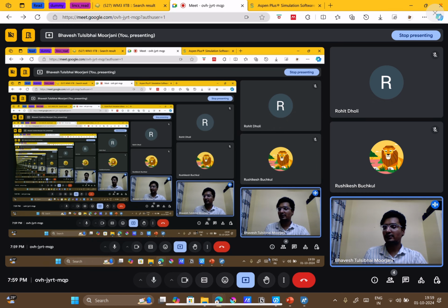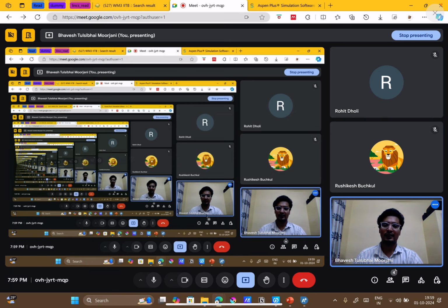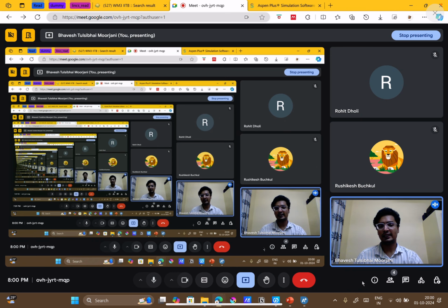So water is used to separate acetone from this mixture. So acetone has an affinity towards the water rather than the ethyl acetate. So acetone will be part of the extract, while the raffinate will contain mainly ethyl acetate and some amount of water and acetone. Okay, so this is how it is, if I want to put it in extraction terms.